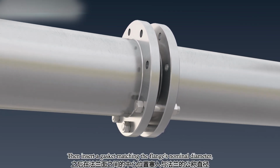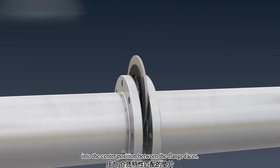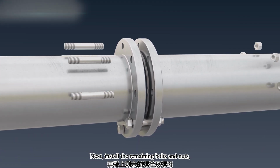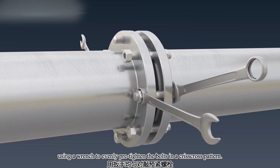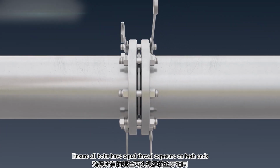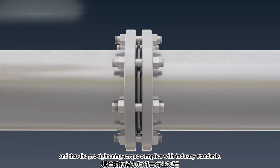Then insert a gasket matching the flange's nominal diameter, pressure rating, and medium characteristics into the center position between the flange faces. Next, install the remaining bolts and nuts, using a wrench to evenly pre-tighten the bolts in a crisscross pattern. Ensure all bolts have equal thread exposure on both ends, and that the pre-tightening torque complies with industry standards.